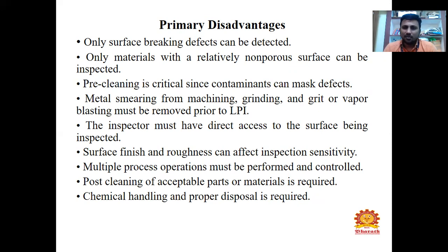Next, surface finish and roughness can affect inspection sensitivity. Multiple process operations must be performed and controlled. Post cleaning of the acceptable part or material is required, and proper handling and disposal of chemicals is required. These are the major disadvantages of the liquid penetrant method.